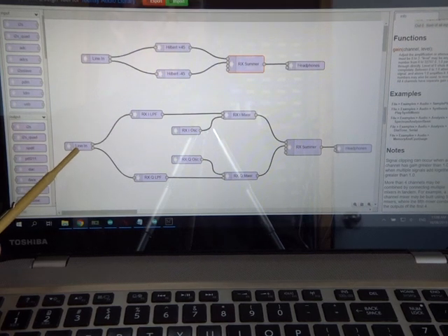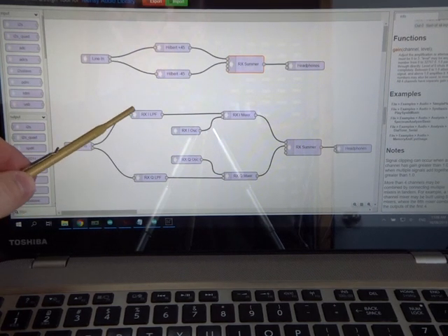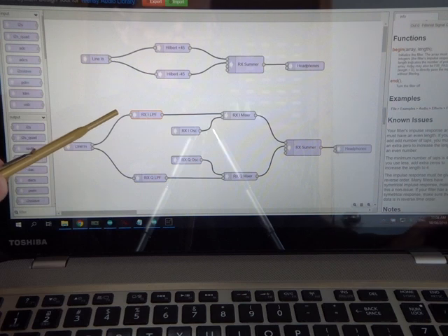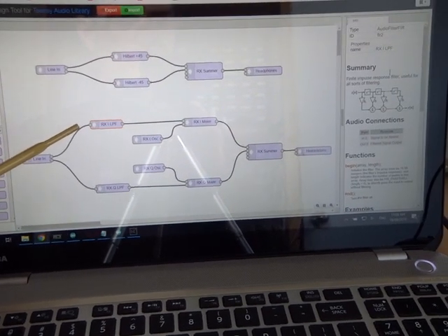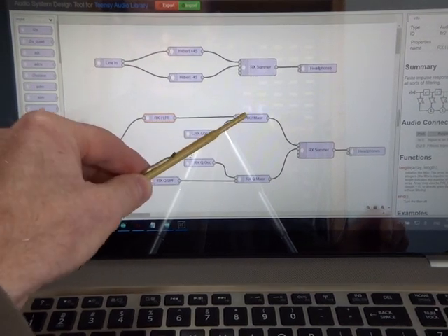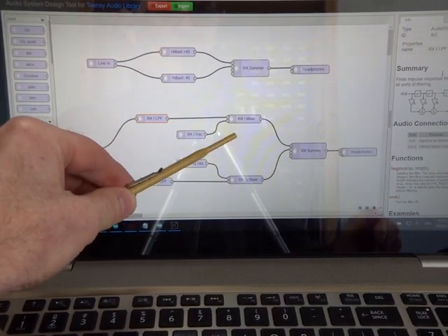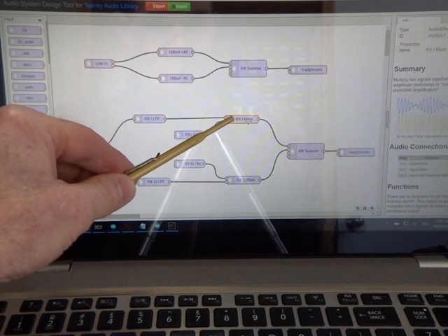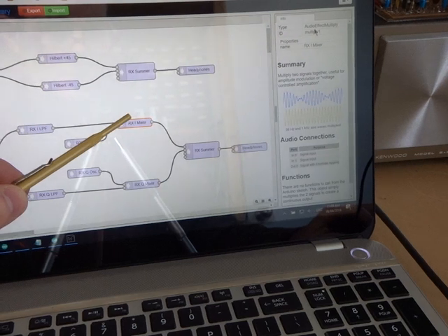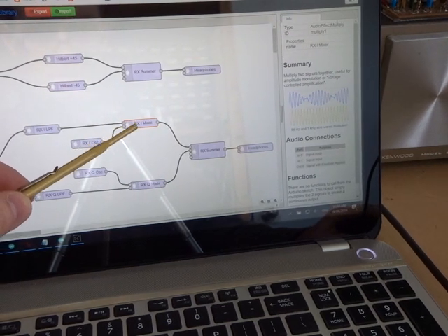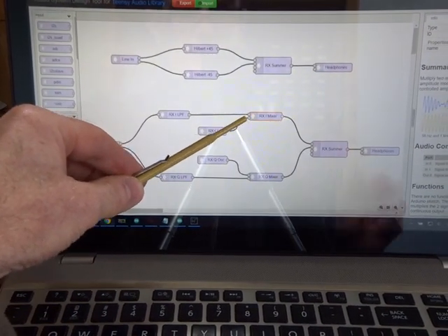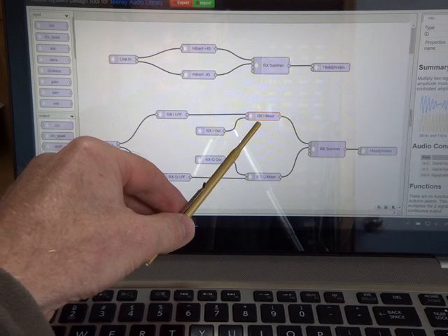Again, our audio is coming into the Teensy through the line in. It's going to two low pass filters. Again, if we were to click onto those, you would see that they are again FIR filters from within the library, on the right hand side, and then those are feeding into two mixers. Within the audio library, they are multipliers. So if we click on that, we can see on the right hand side the object name is actually an audio effect multiply. So multiplying produces the same effect as a mixer in the analog domain.